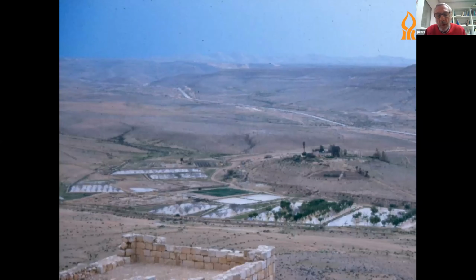And the water is ponded and infiltrates them. What is not possible to see in this picture is that the average water depth here is 40 or 50 centimeters, which means that when you have one runoff event, you can fill each plot with around 500 millimeters of water, which is usually enough for one crop, particularly if we're talking about trees.